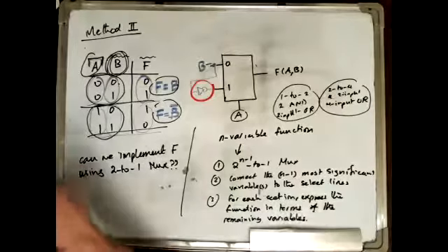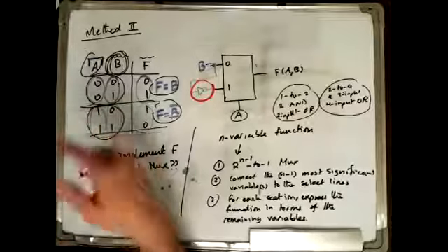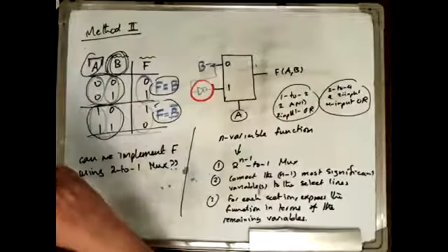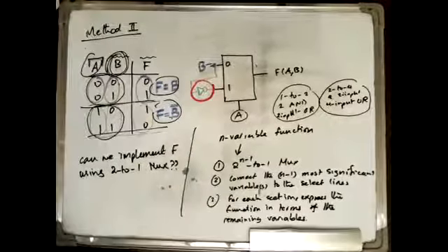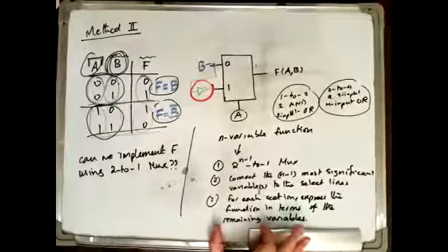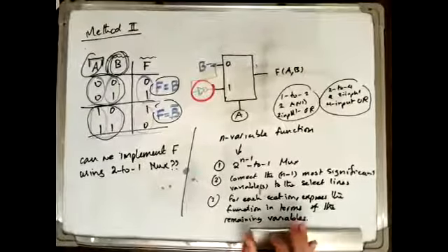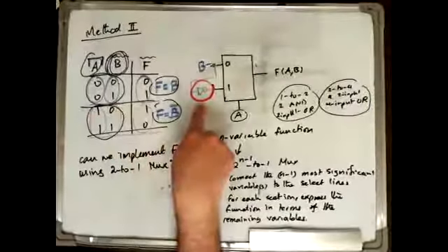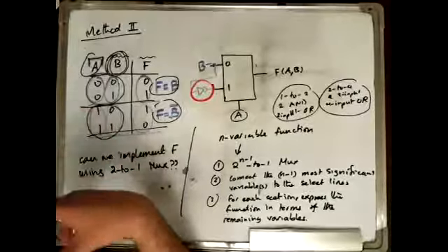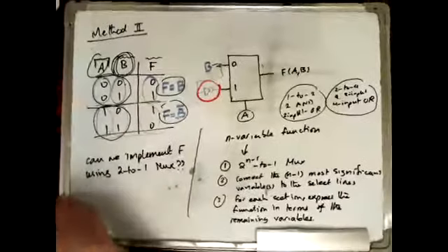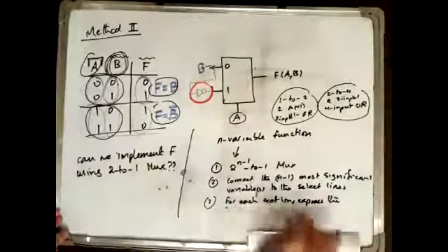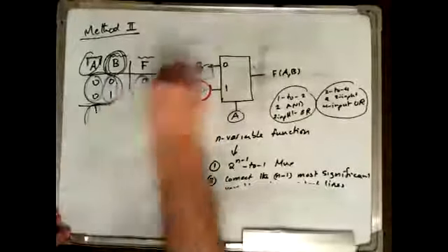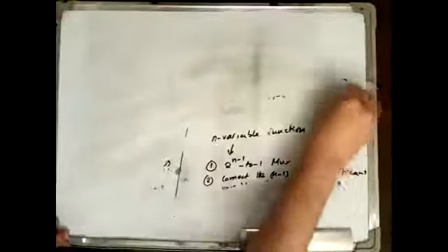So very simple. And you can extend it to method 3, method 4, method 5, which is basically you keep decreasing the size of the multiplexer. However, in this case, you will start to use more of the least significant variables to express the function, and you will need more than an inverter. You will need maybe an AND gate, an OR gate, an XOR. So let's take 2 examples. We're running out of time.